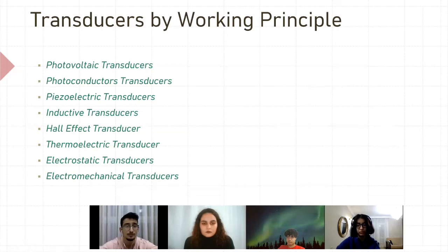The Hall effect transducer detects the magnetic field and converts it into an electrical signal proportional to its size. Proximity and position detection, and speed detection in tachometers are the usage areas of Hall effect transducers.